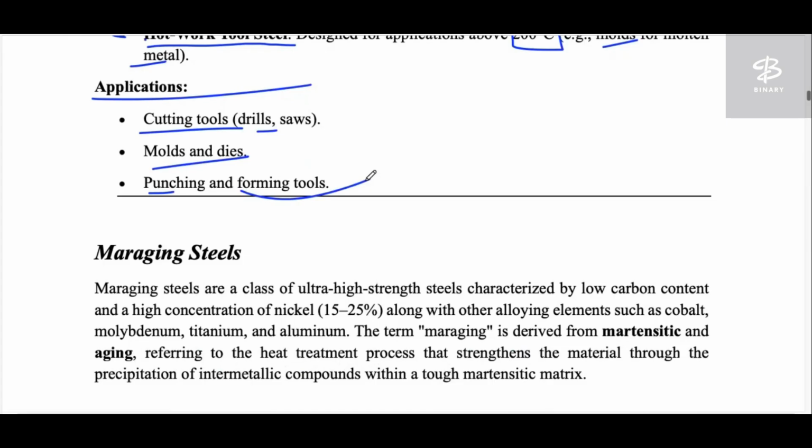So it is the same process, but it depends on your objective. According to your objective, the process is defined. If your objective is to get the punched piece as the final product, then it is punching. But if you are concerned only with the sheet that remains after punching, as your final product, then it is known as blanking.